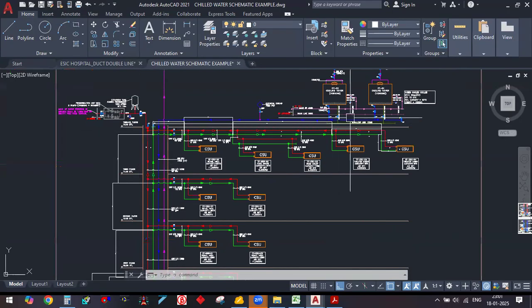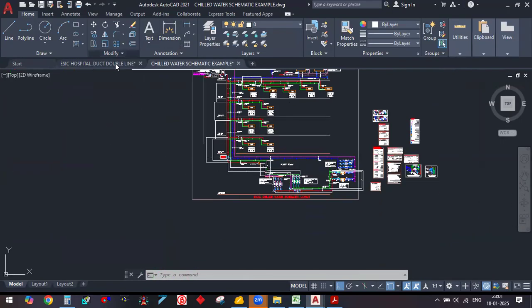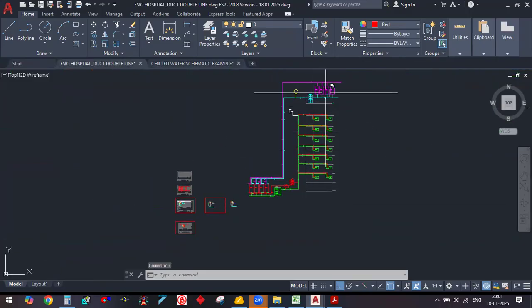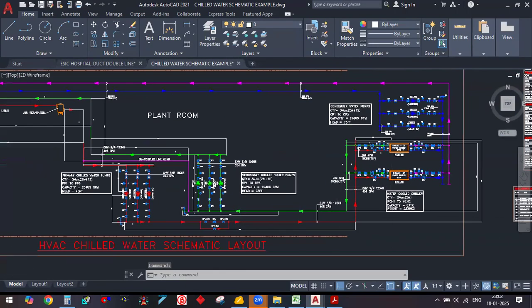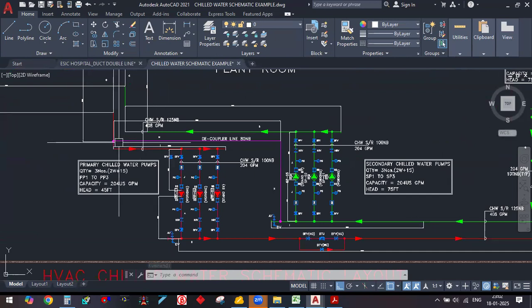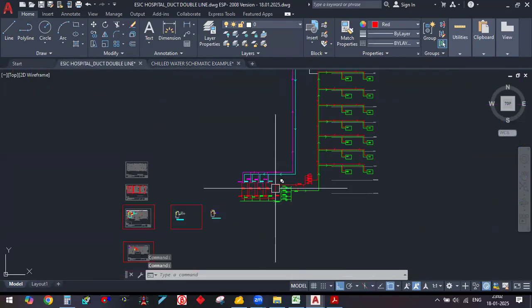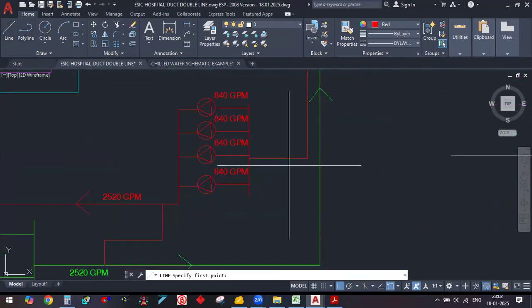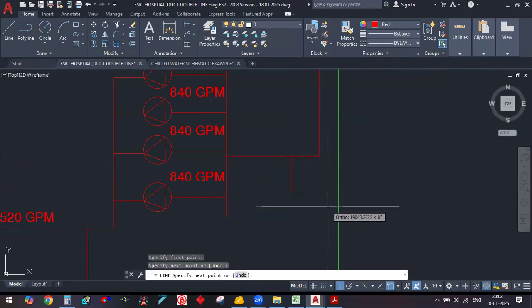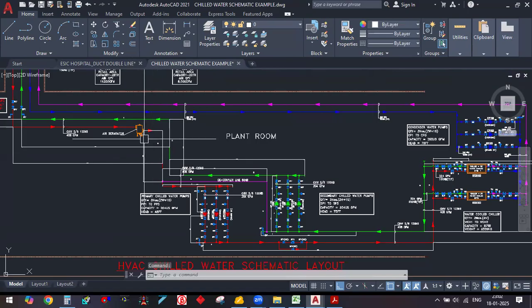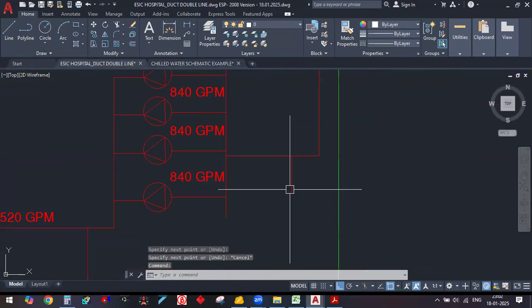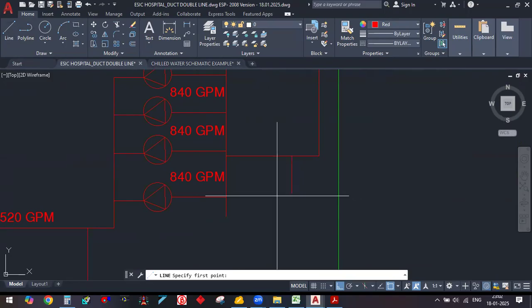Okay, but see, from cooling tower to chiller. So you see here, from cooling tower to chiller and from chiller to the equipments. Now my decoupler line is between the headers of these two. Okay, so air separator, yes. A specific area, means the air separator is installed here on the return side, means we have to install it before the pump. So at this point, we have to install the air separator. See here, they have installed the air separator, so I'm also going to take it somewhere here only.